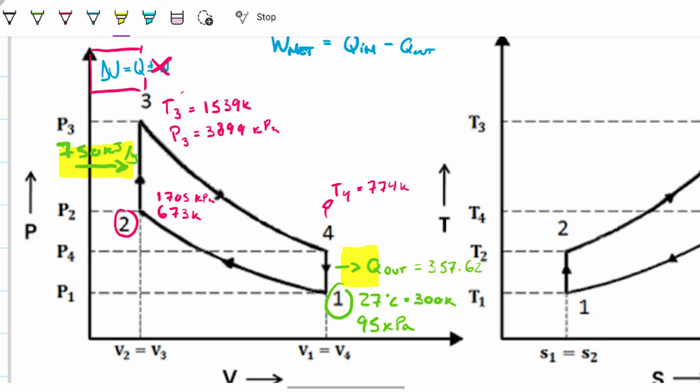You can see, for instance, that the pressure 1 is the smallest one. Then we have pressure 4, then pressure 2, pressure 3. So if pressure 2 is not between pressure 3 and pressure 1, we have a problem. It's not the case. We're good here. What about temperature? Well, as we're compressing, you would expect the temperature to increase, and here we're giving energy, so we also expect the temperature to increase.